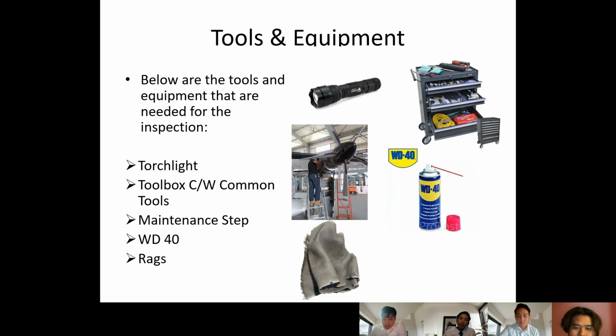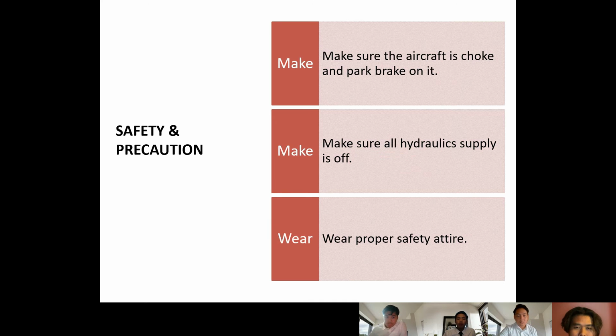Now, followed by Muhammad Nakune to continue about the safety precautions. Now we go to the next slide, safety and precautions. First, make sure the aircraft is chocked and the park brake is on. Second, make sure all hydraulic supply is off. And third, wear proper safety attire.